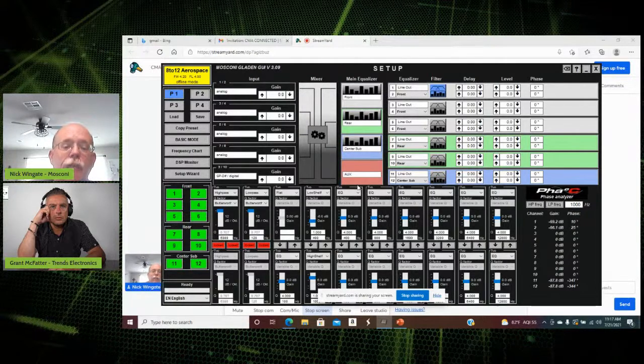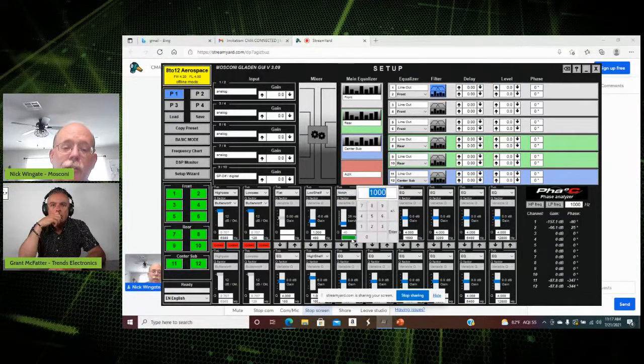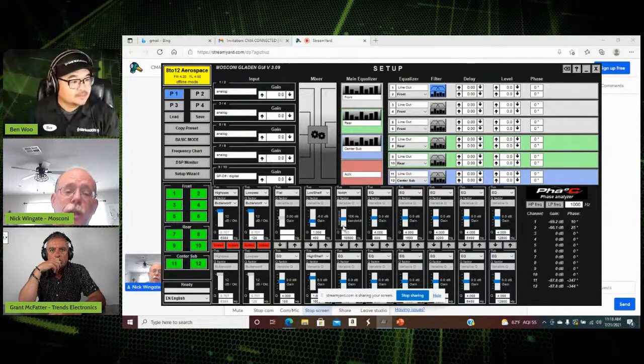Let's say we've got a tweeter. I'm going to change it because normally I've got my tweeters, if I'm going fully active, out of channels 1 and 2. And so what I will do is, if I find this nasty reflection happening at 10,500 hertz, which a lot of times that's what it is. That's just experience. I'm just telling you, experience tells me this. Okay. And I'm going to turn it down. Yes, I know. And I'm going to go start looking for it.